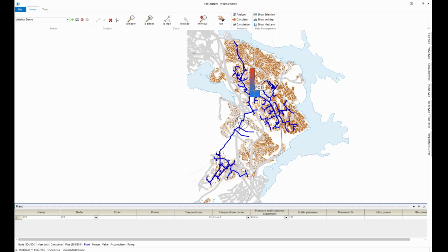There's always one that will take up the difference in load, so most of the time you will have all the other production facilities set at a set production rate or power outlet, and then one of them will be controlling to make sure you have enough power to all the customers.